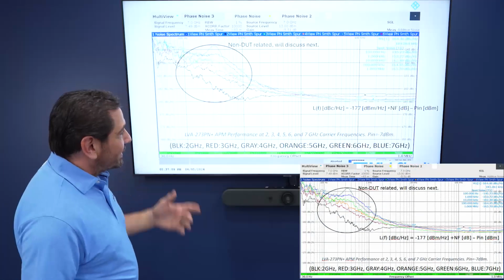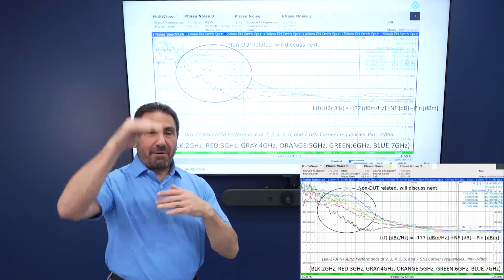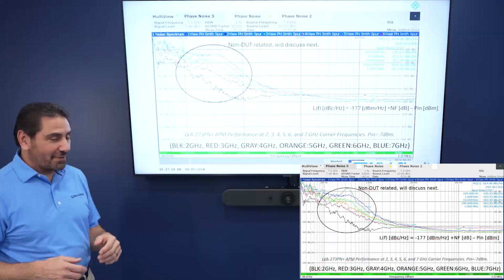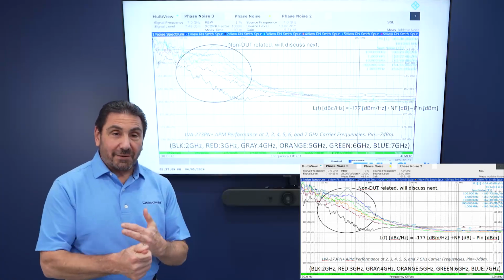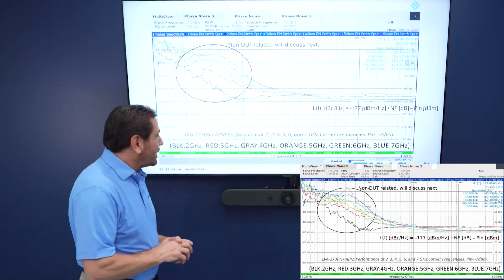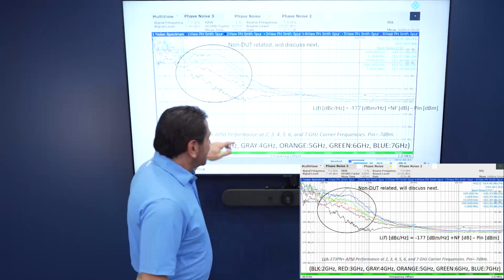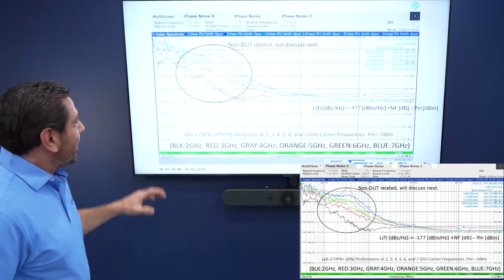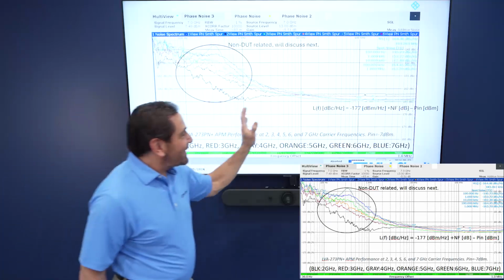So let's go back and say, all right, let's take some measurements of those 2 states, the low power and high power. What's low power? Well, in this case, we have an LVA 273 PN+, which is an HBT distributed amplifier working to 27 gigahertz, very, very broadband. And we're measuring it at different frequencies at a fixed input power of -7. So what do we notice here? Ignore this. We'll get into this later. But what do we see out here?